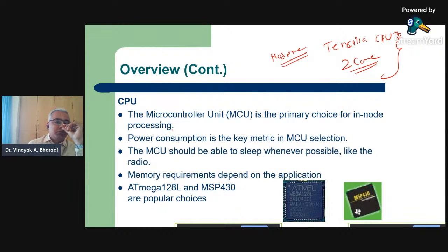So there is a brief difference between a microcontroller and a central processing unit. The main difference is that a microcontroller is a single chip CPU. It has its own RAM, its own ROM, and it can directly interface with the hardware, and it can be flashed and run. With a CPU, you might have to connect additional RAM, maybe through the motherboard circuitry.